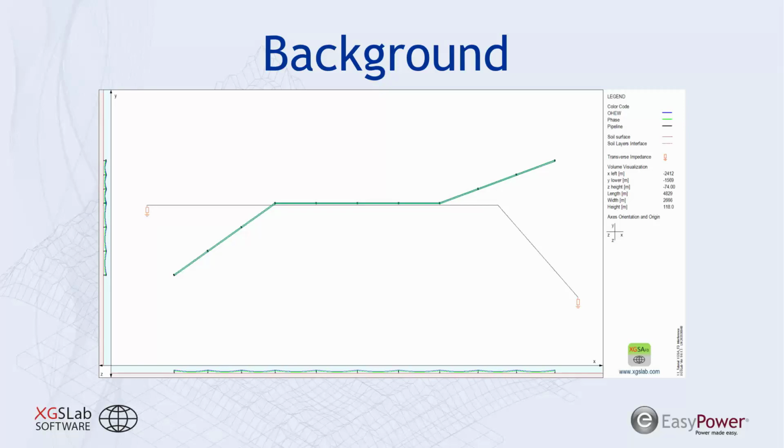And the exposure length of this transmission line on the pipeline is approximately 1 mile, where we're directly parallel, and we will have some effects as the transmission line crosses over the pipeline and then departs away from the pipeline. And we'll see that in our voltage plot on the pipeline, as well as our amps per meter squared plot of the pipeline.